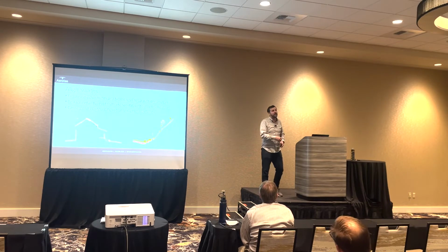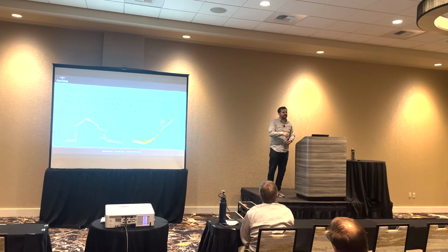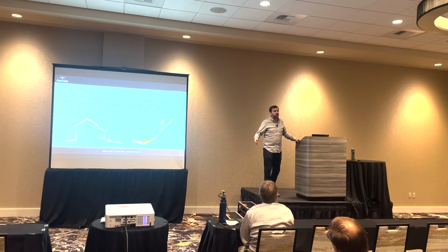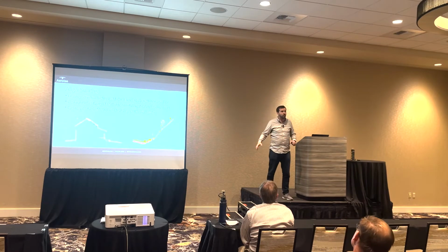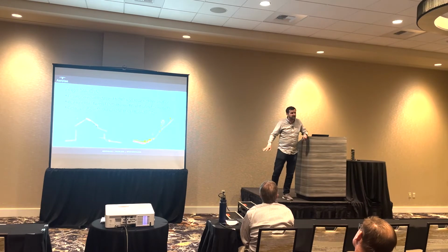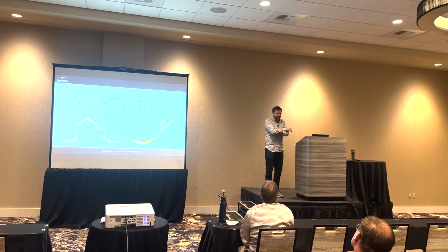You might measure that point, and you need to post-process that, and then come back into the field and set it up and key it in, and that's a bad workflow itself. So very often what we try and do, and this is back on the workflow side of things, we try and create the most robust workflow out there, which means it doesn't rely on having a known point. If you do, great, use it, but it doesn't rely on it, so that you can actually go up, set up over any point whatsoever.